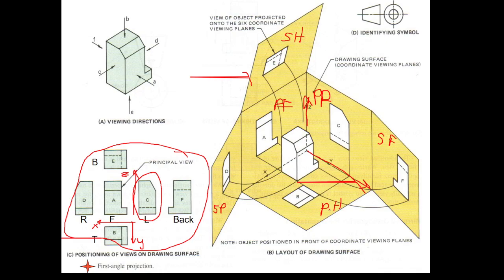While we are rotating the profile and horizontal picture planes, if the y-axis is attached to the horizontal picture plane, it finds its place vertically oriented in the down direction. But if the y-axis is attached to the primary profile picture plane, it travels together with that picture plane and finds its place horizontally oriented, extended to the right.